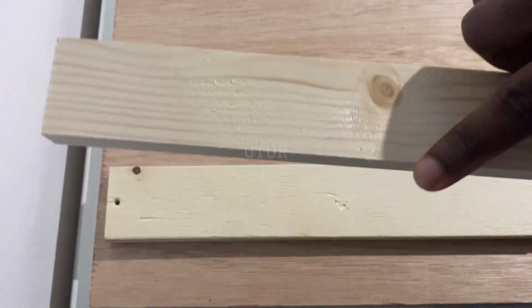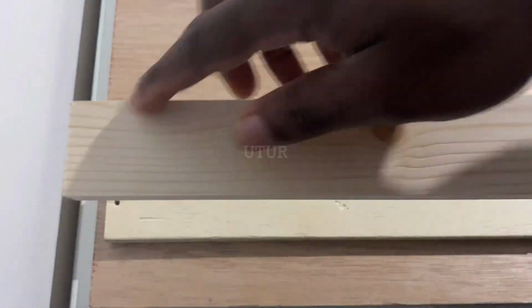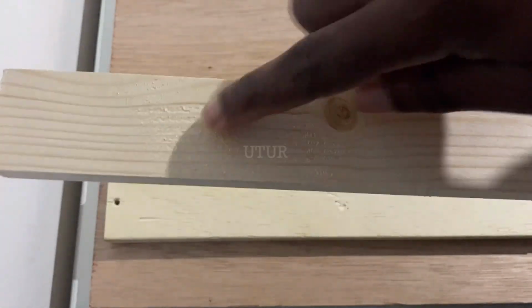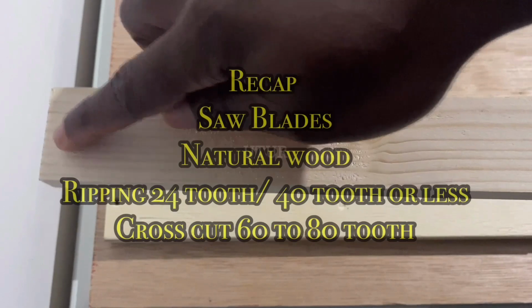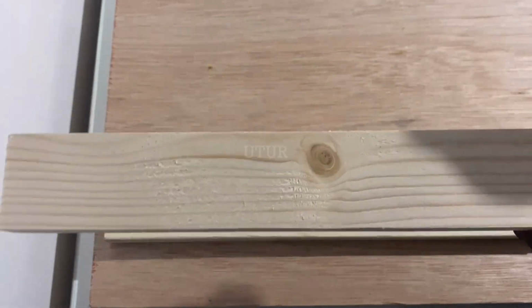So essentially, you're cutting across the grain to achieve a finer cut. Do not use a cross-cutting blade for ripping applications. And that's because if the gullet isn't big enough, it may not be able to excavate material from the gut, which leads to overheating. And so for ripping, you want to use 40 tooth or less, or typically 24 tooth. And for cross-cutting, 60 to 80 tooth.